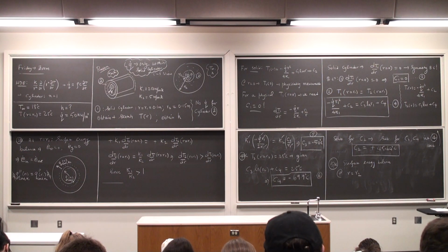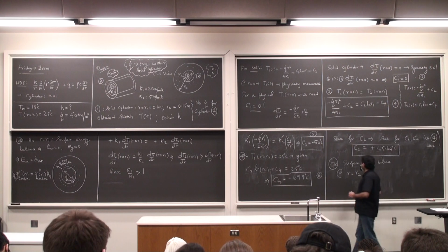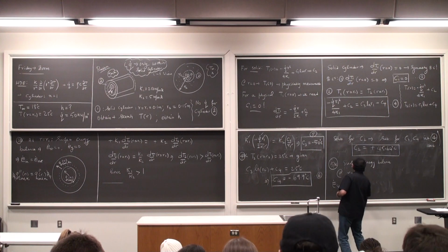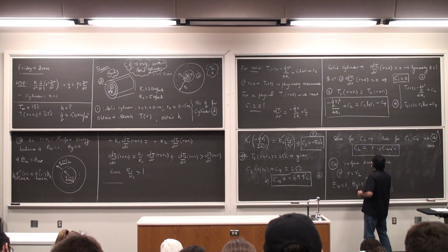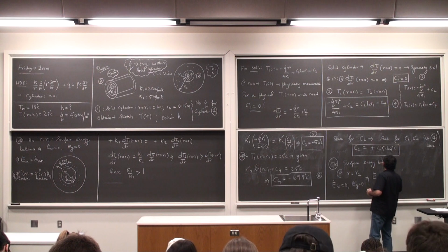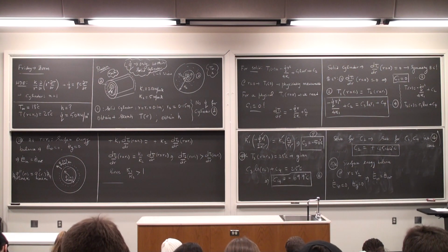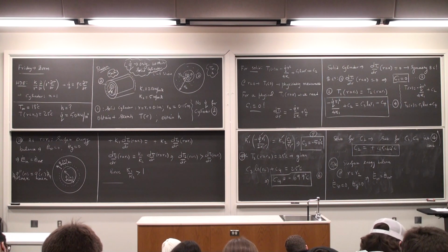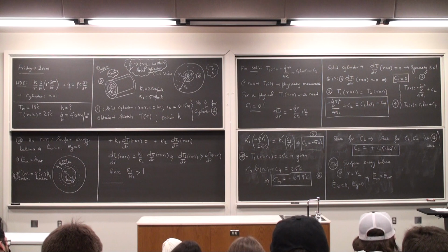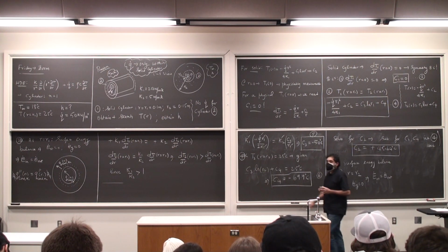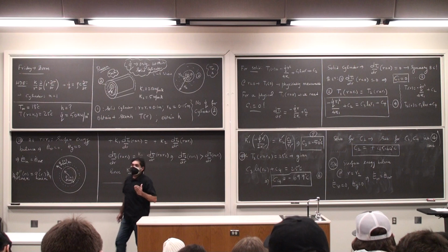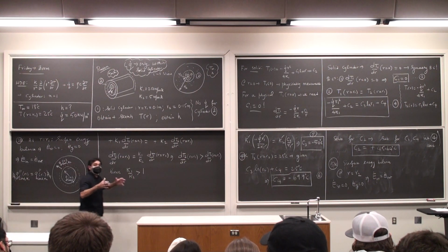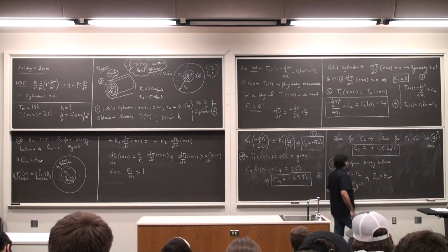When you do surface energy balance, E dot stored and E dot generated is 0. Which implies E dot in is equal to E dot out. Draw my control surface. I need to see these steps. If you're doing a surface energy balance, you draw a control surface and you show me what's going in and what's coming out. Okay? So I need to draw something like that for the outer ring as well. Let me do that here.